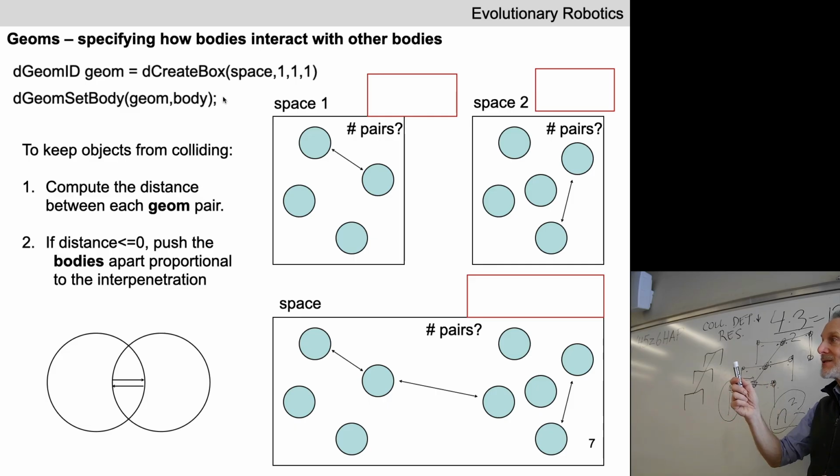If we created one simulation, which typically requires just one process running on your laptop, that's good news. But now we have to create 50 spaces, and we're going to put the robots really distant from one another inside the virtual world. So these spaces are never going to come into contact with one another, we hope. Have we alleviated the burden on the physics engine? It turns out the physics engine still has to check whether these 50 spaces are colliding or not. It doesn't know. So there's an additional computational effort required.